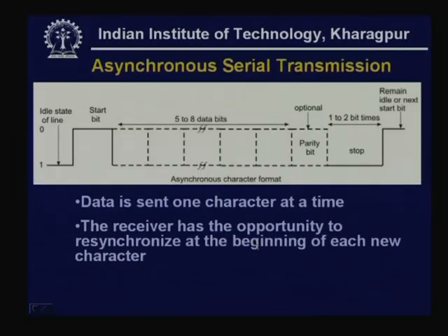Whenever data is sent by the sender, at the receiving end it has to be received in a synchronized manner, so that a 1 is received as 1, a 0 is received as 0 at the proper bit position. If it is not received in that manner, then it will be incorrect. Here, as you have seen, it is synchronized with the help of the start bit; at the middle of the start bit, and then it is sampled at the middle of each of these bits. As a result, it gets synchronized with this particular rising edge, and then at the middle of each bit the data is sampled to find out whether it is 0 or 1.